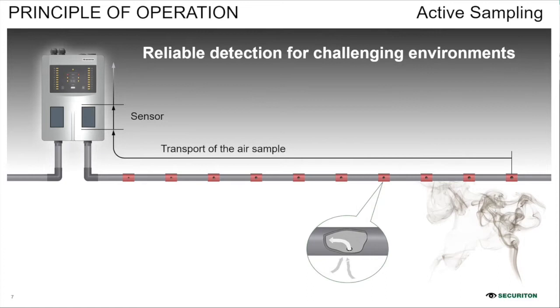For example, spot detectors or point detectors will work only when the smoke enters the chamber of a detector. It is a passive device and waits for smoke to enter the chamber. And aspirating smoke detectors don't wait for smoke to enter the chamber. They keep drawing air continuously from the atmosphere, and whenever there is any smoke inside the chamber of the detector, it gives you an immediate alert.